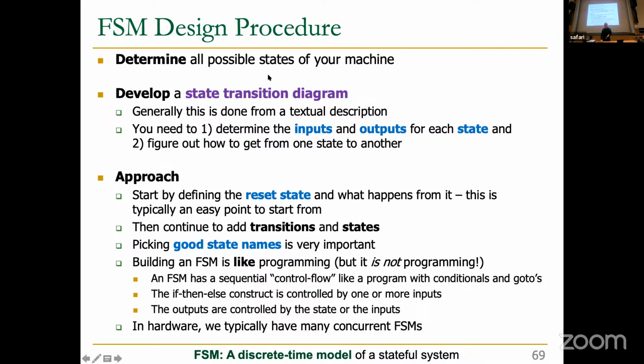You need to determine all possible states of the machine. You need to develop a state transition diagram. And this is generally done from a description of what should happen. And clearly, this should have everything: inputs, outputs for each state, as well as how to get from one state to another. And don't forget the reset.